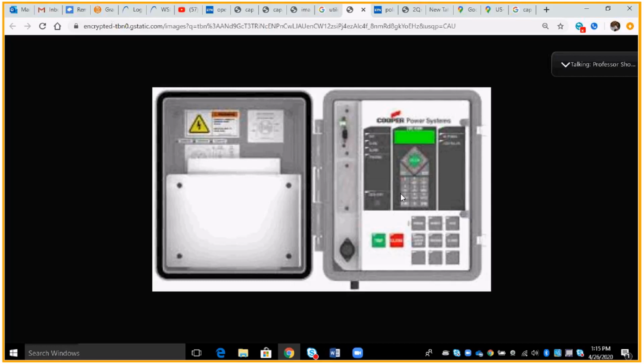If the substation recognizes that the power factor, and you saw those waveforms before, is bad, and we have a large inductive load, it's going to send a radio signal to this control box mounted on the pole, and that control box is going to close the vacuum bottles. Vice versa, if the substation sees there's too much capacitance on the circuit, it's going to send another signal to this box and say open. And this box is going to send a signal up to the vacuum bottles, and they are going to open up.